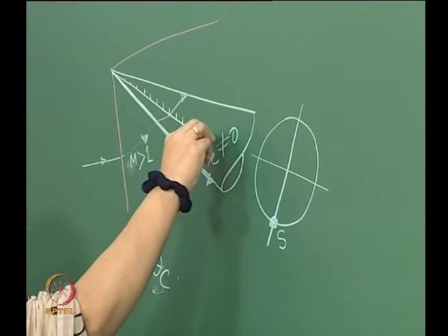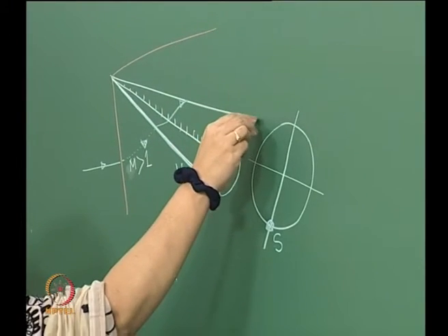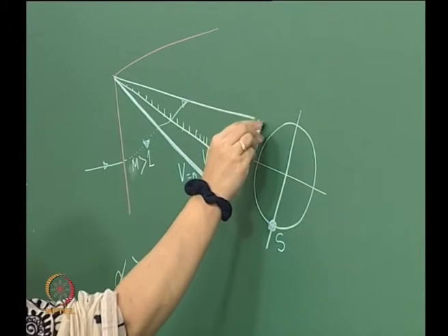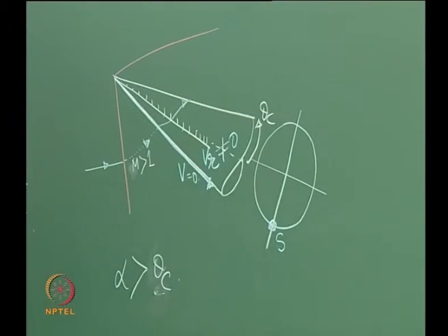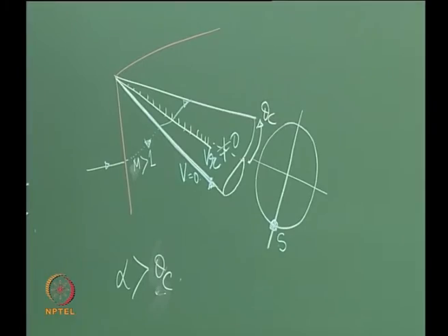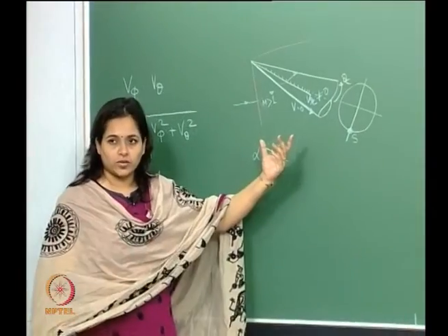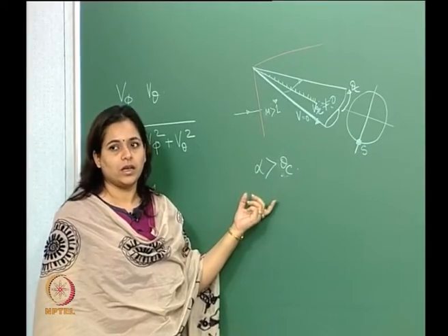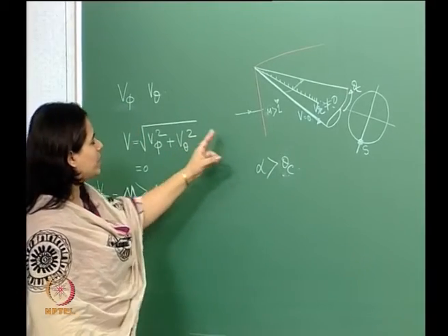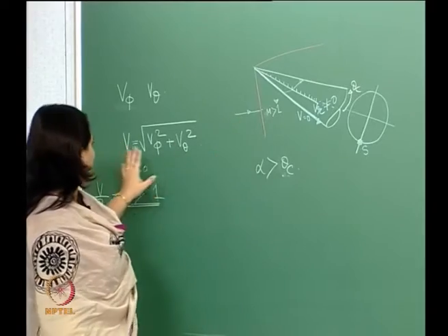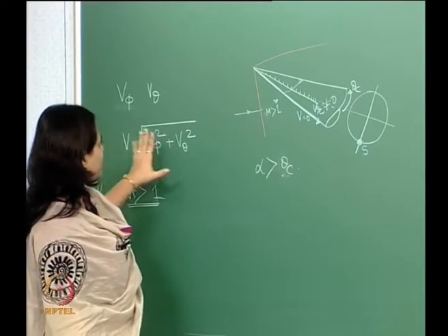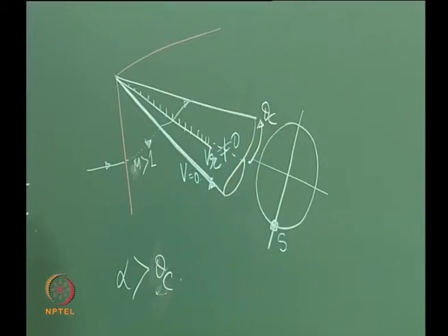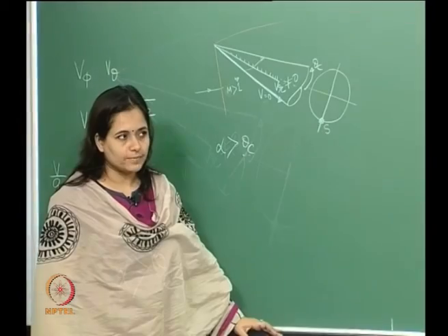Yeah, actually, I cannot draw it here. So this is my theta c. Half cone angle is your theta c. This embedded shock will happen most of the time for a very high angle of attack. A very high angle of attack will end up increasing the velocity, and if this becomes supersonic, we have these embedded shocks.